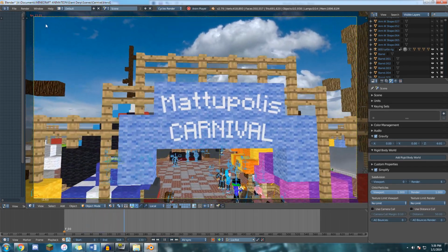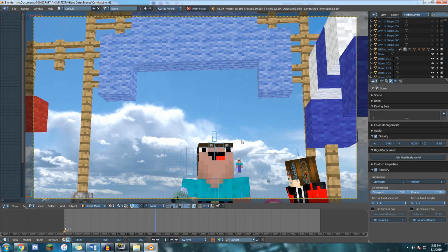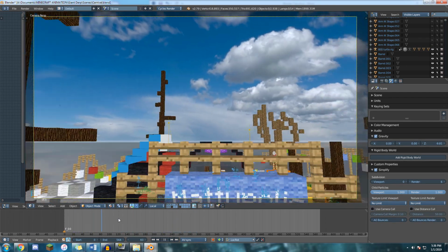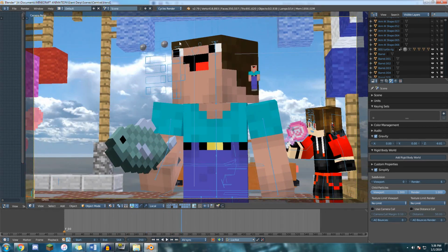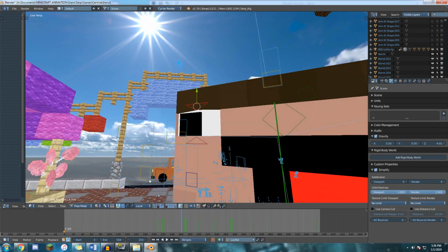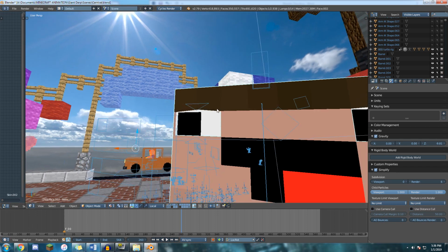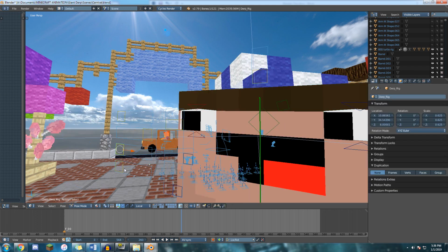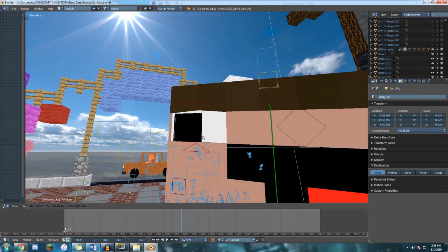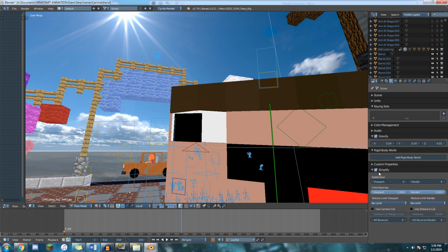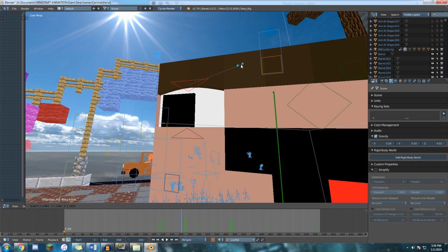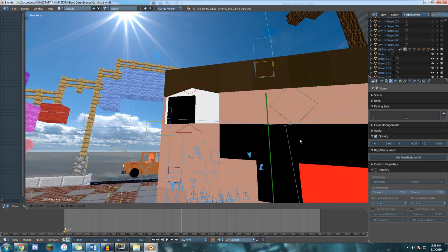That basically doubled our frames per second on a scene which is already pretty laggy because there's tons and tons of rigs. And what that is doing is, if we have a character, or it could be anything at all, if we have something in our scene that has subdivisions, for example this face has a subsurface modifier on it, and that subsurface modifier controls how curvy some of these things are. Let me actually turn that back off. So you see how he's got a nice curvy eyebrow, but then if I turn it off, it's sharp.